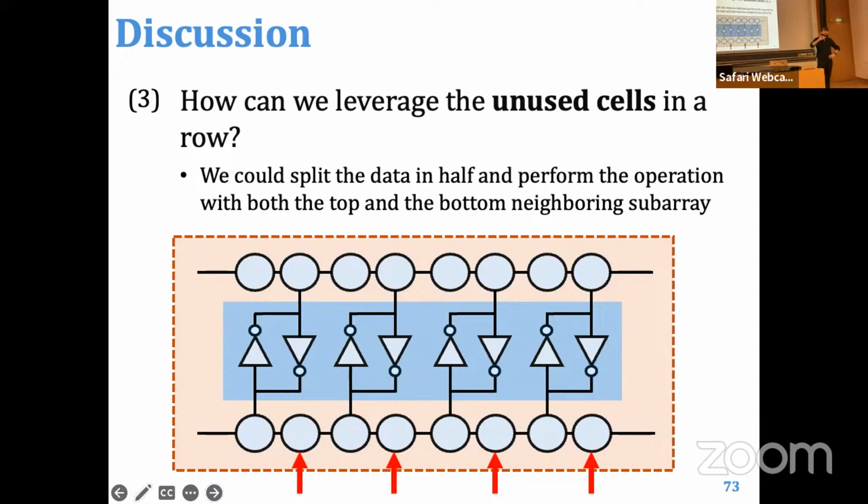So the only thing that you gain is that you move the data once. You put the data in the middle rows only once, so you don't have to copy. Because it has a destructive nature, you were going to form two reference subarrays either way, either serially or in parallel. So then you just save the time to do the formatting and to put the data there twice.